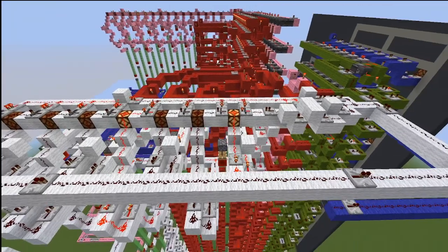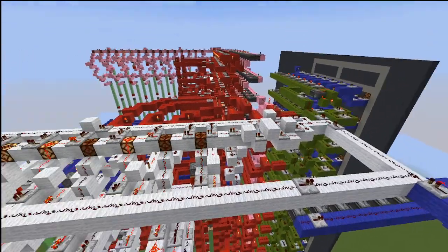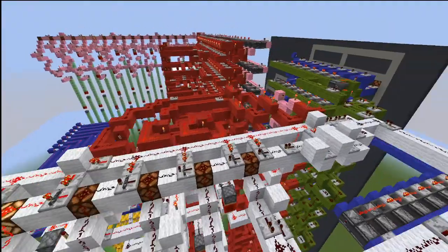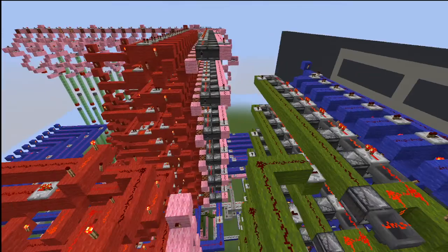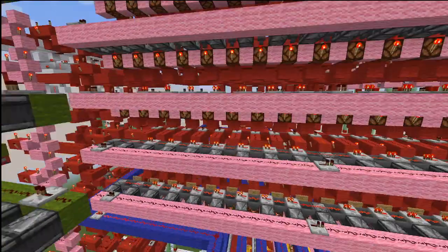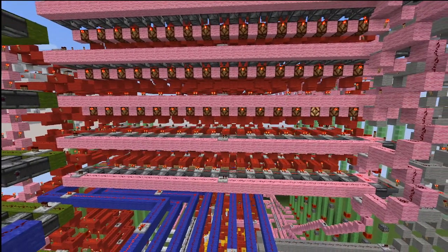Sure enough, it read a 9, and now it's going to select from prom line 9, which has the program code for out, as you can see here. So now we can see, if I come over here in time, we'll also be able to see the instruction register update the control unit.